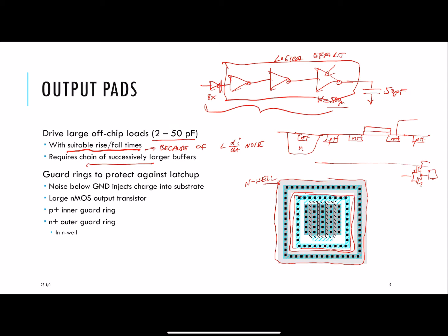So you think, well, what good does this do you? You could go through the substrate and get noise out to other places. It turns out that they do a shallow P plus doping everywhere on the surface where you don't define anything as a designer. They just do that P plus implant, and so that's a good way for noise to get around the chip. So by having these kind of breaks in that P plus layer really helps you out. And also if you're in an epi process, like we talked about, the epi thickness might be 5 microns or something. So the guard rings do help you.